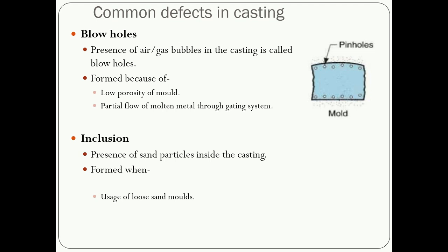Major defect means if that defect has occurred in the casting process, then that casting is susceptible to scrap. Means the chances of that casting becoming scrap will be more. That is a major defect. A major defect does not have any kind of repair.